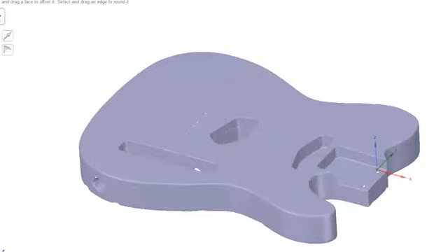And I go over to the capture ribbon. Inside of here, just a quick highlight to make this fast, but after you connect and scan using the acquire section, you can edit by selecting. You can align the scans together. As many of you know, when you scan an object, many times you have to scan it in more than one position to capture all the geometry.